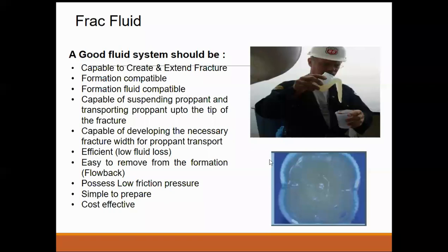So now when this frac fluid is prepared, there is one additive which is added called breaker. So now why do we need a breaker? Because whatever fluid we have pumped into the formation, we do not want it to stay there. We want it to flow back so that it cannot cause damage to the permeability that you have created, or the proppant pack permeability that you have created over there. Okay, so you have to remove that back. So for the removal, you have to break the fluid.